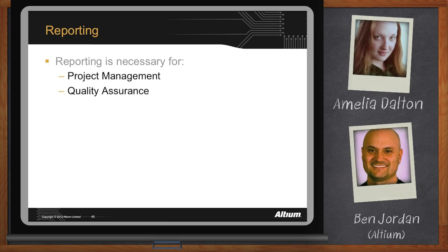Obviously, as we mentioned earlier, it helps with standards compliance and the ability to get your designs and your products certified, particularly if it's in the high-rel industry or aerospace, where you need to generate an output that says, okay, here's a specific change we made to the source files, and the reason we made that change is item 10 in the requirements matrix that said there shall be no dead code in the memory of the CPU, or whatever it happens to be. Every time you check in or make a tag or do a branch of the version control, you can keep some record of that and generate reports from that.